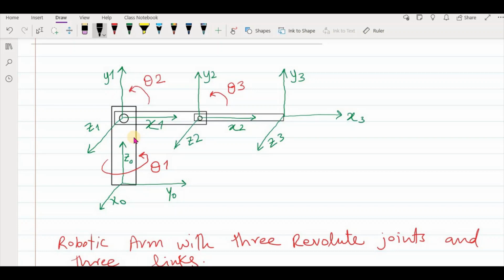Here you see we didn't do that because the rotation must be along the axis. So in this case, x will not get priority, but if possible, try to give the link length toward the x-axis. In this case we have a chance because the rotation is about z-axis, but length can also be placed about the x-axis.